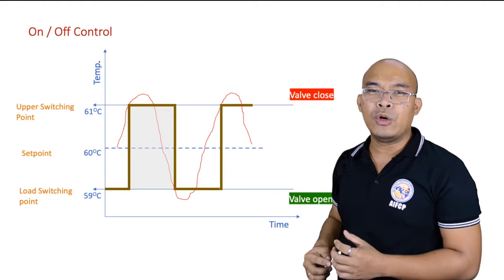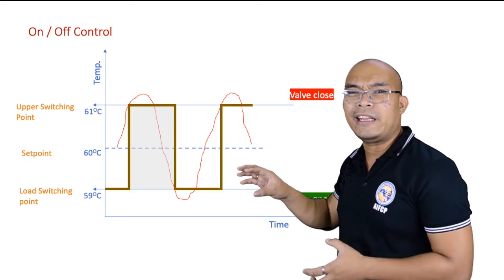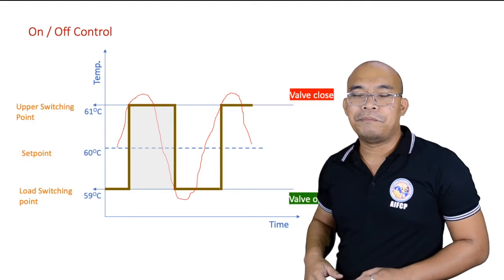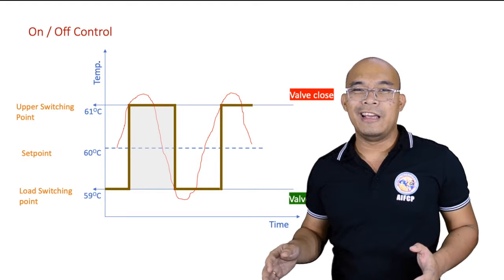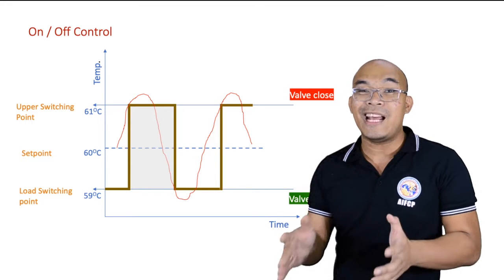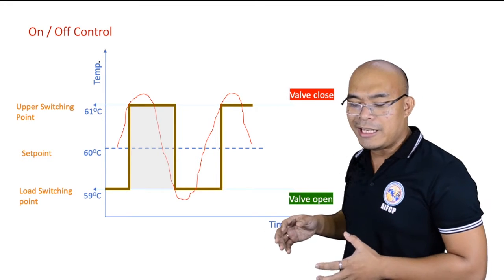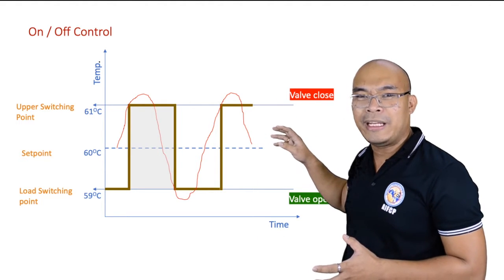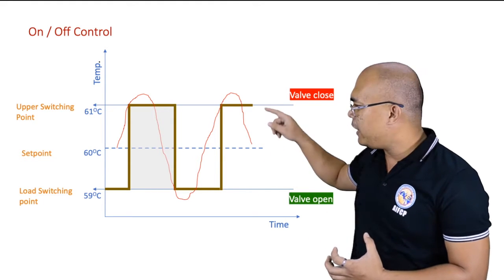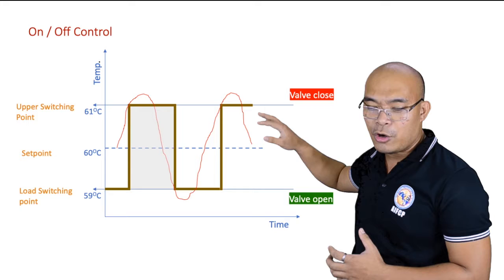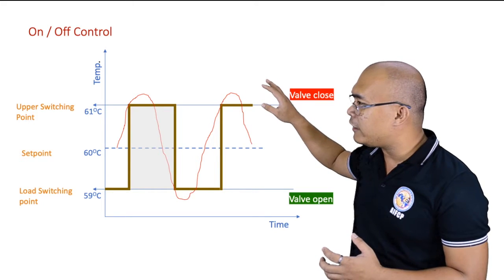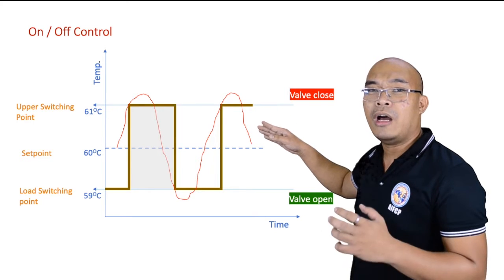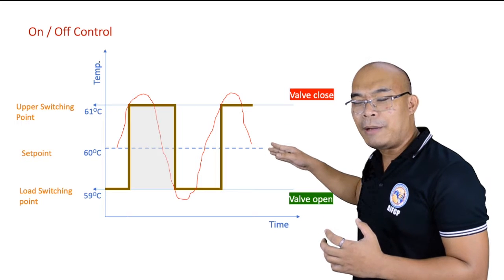However guys, take note, may residual heat ka pa na naiwan doon. So, ibig sabihin, hindi yan automatic, hindi yan kabayo na pag sinabi mong titigil na, titigil agad. Hindi yan automatic na ganyan. It takes time. It takes time to adjust. So, in this particular case here, pag yung temperature mo, nakaabot na ng 61 degrees centigrade, due to the residual heat in the system, mag-i-increase pa yan. Nag-i-increase pa, di ba? Nag-overshoot siya. So, yung overshoot niya na ngayon, increase ba yan? And then, to the point na pag na-reach na yung peak, okay, bababa na yan, kasi pinatay mo na yung steam na nag-supply sa kanya. So, pababa na yan, pababa ng pababa.